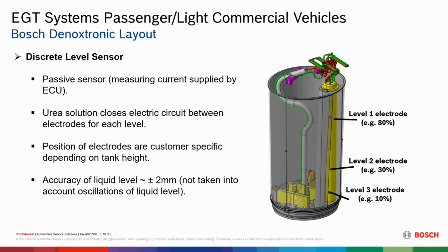Well, the problem with that is when it starts causing that issue, it can put the vehicle into different modes that the operator's not going to like too well. So they put systems in here that they're not going to let these systems run low. If it runs low, they're going to put the vehicle into different conditions to where the vehicle may just idle or not even start in some cases if it's empty. So if the tank's full and it thinks it's empty because the level sense is defective, guess what's going to happen? We're going to have drivability conditions that are going to affect it.